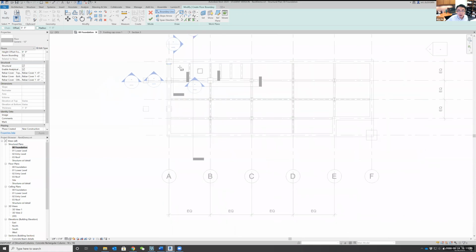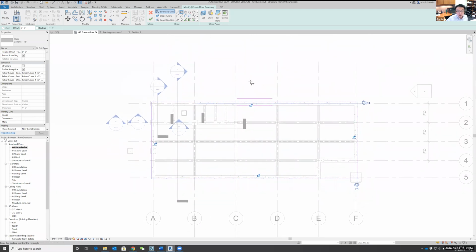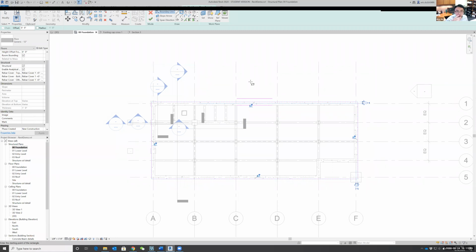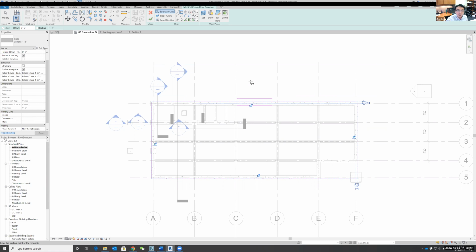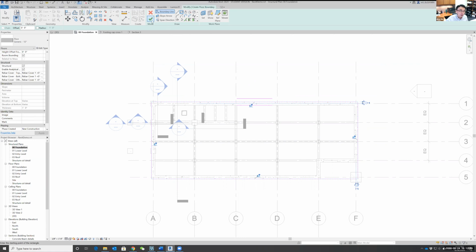So basically we are telling Revit that I know there's a floor, but it's actually my architectural floor. Now I'm going to tell you I also want this to be my structural floor. So that's different in Revit for 2 reasons. Number 1 reason is, remember, Revit architecture and Revit structure used to be different programs. So they have different definitions, different codes. The other thing is when you are performing structural analysis, the behavior of the architectural floor and the structural floor will be very different in your analysis. So when this is done, click OK.